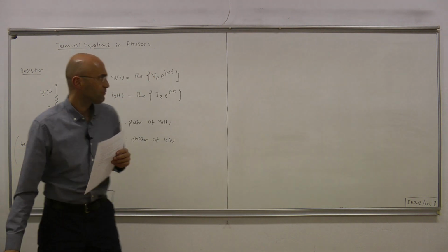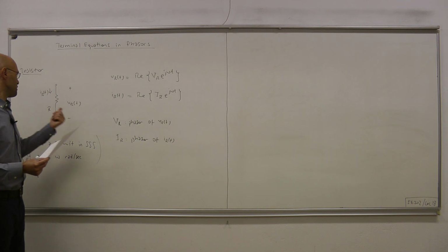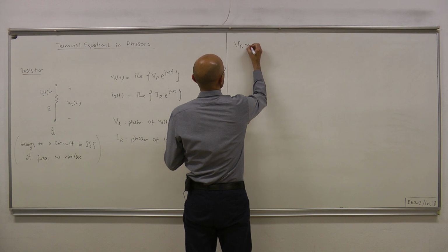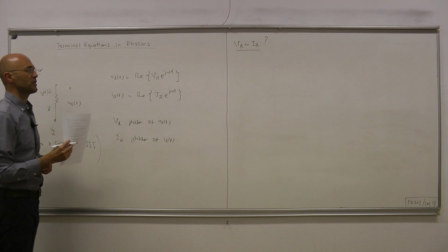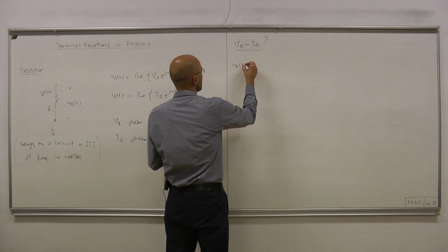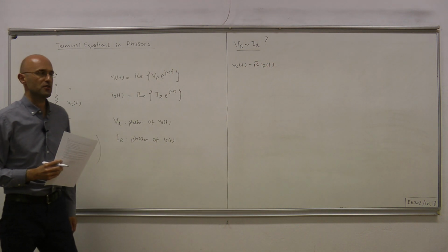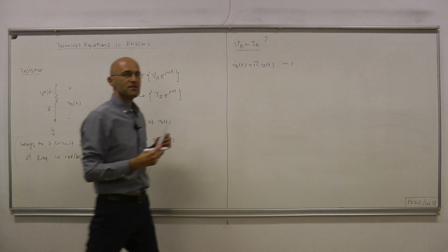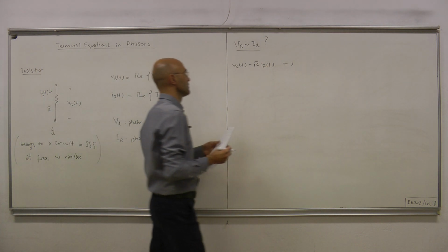All we have to do is take these expressions and apply to them the constraint, which is Ohm's law. So what's the relation between the phasors of voltage and current of an LTI resistor? Okay, we begin from Ohm's law: voltage equals resistance times the current. And then we write the voltage and current using this representation.